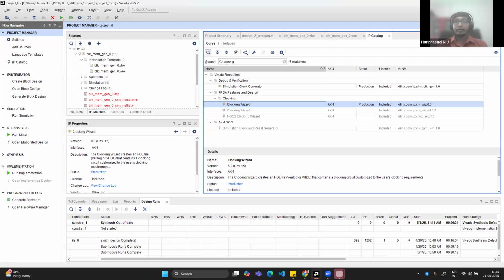PCBs can be faulty, once we fabricate them. Usually with these BGA packages, ball grid array packages, when we fabricate, they can be faulty. But very rarely have I seen the manufacturing side be defective, because after one round of validation, the defects are caught.